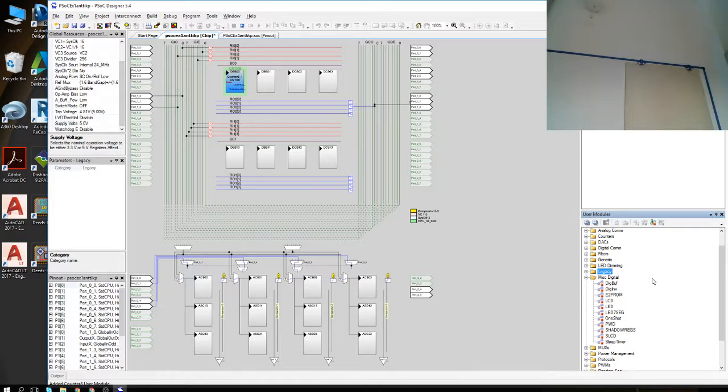So by using a shadow register, you always write the value you want to that volatile kind of register. You write your value there and modify it, and then write the shadow register value to the real register. So shadow is basically your wish of what the content should be.